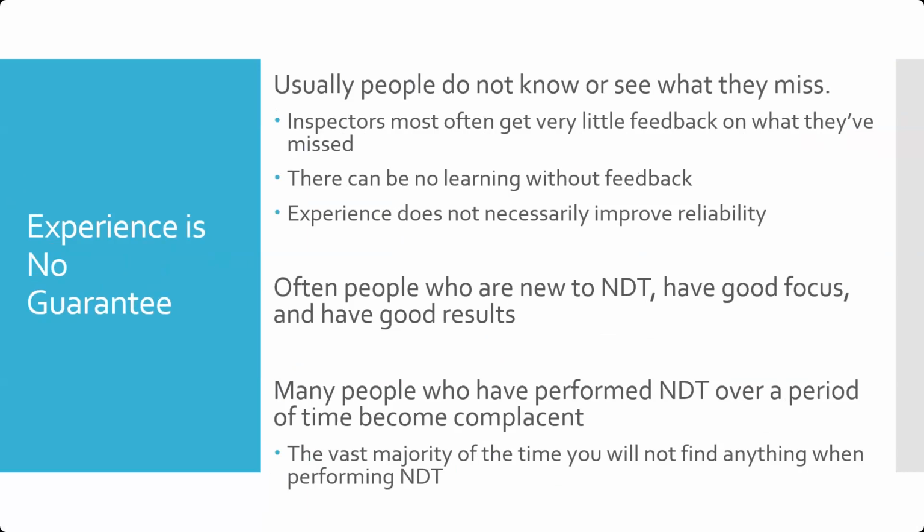I haven't found it 99 or 999 other times. What makes you think this time will be different? And so people often do start to get complacent and just sign off, pencil whipping stuff and not doing a thorough inspection, and that can become very, very dangerous, because then you will have that one time where it turns out that finding something with NDT was incredibly critical.